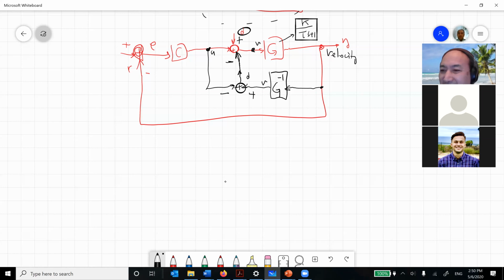The load is like a disturbance. I want the elevator's performance not to be affected by these load changes, the uncertain number of people in the elevator. In this case, you can do this kind of disturbance observer control. This is the idea, DOB, disturbance observer.